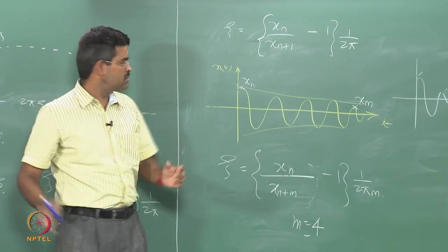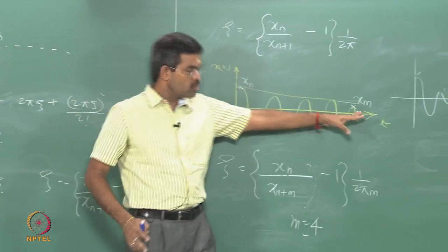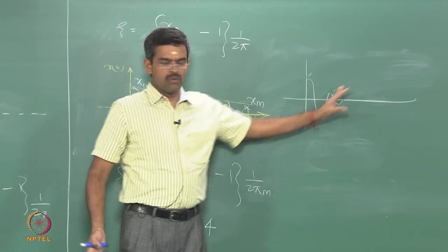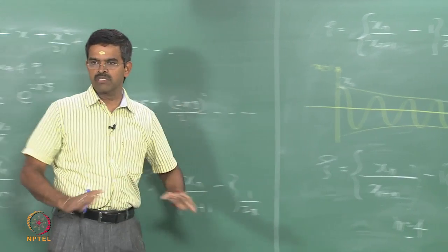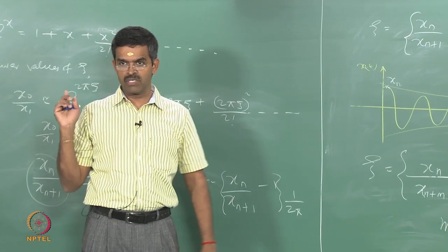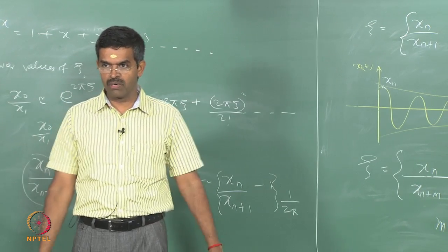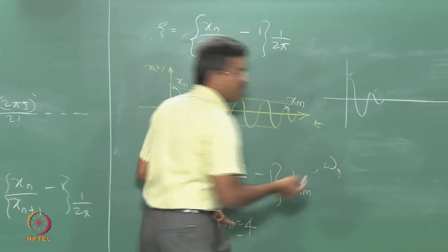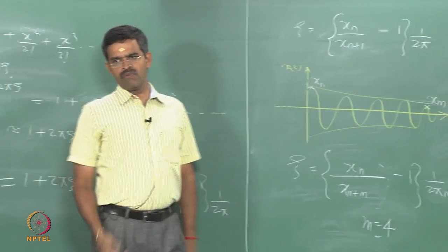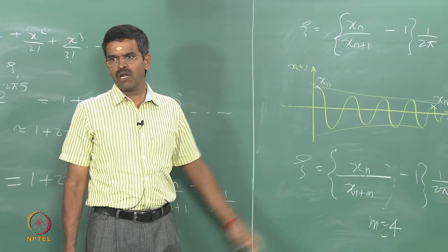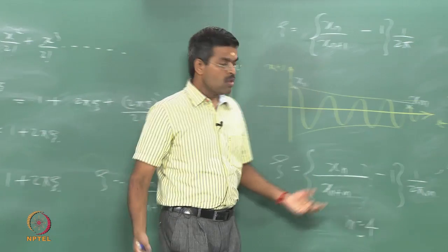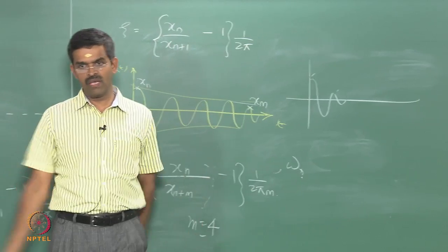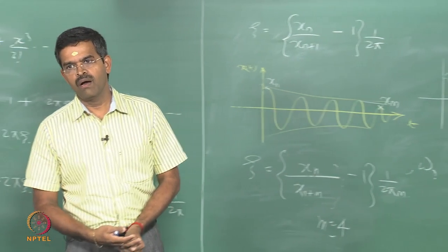But in general dynamics, we are interested to know, is it becoming 0? Yes. How many cycles? Known. What is the value? We know the value. So, we are answering almost all the questions which are unknown in the given equation, but zeta is one of the unknowns, because if you do not know zeta, you cannot find omega d. Omega d is a function of zeta actually. Okay, you cannot find this. So, you do not know what is the damped vibration frequency at which the system is resonating or oscillating. So, we need zeta.